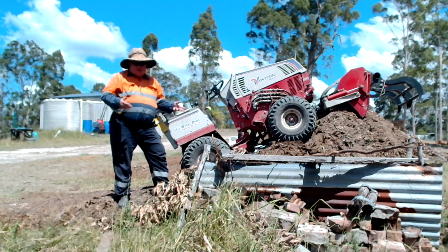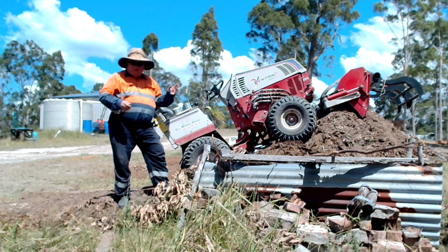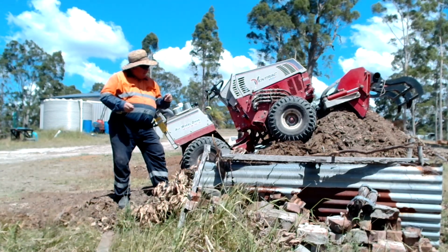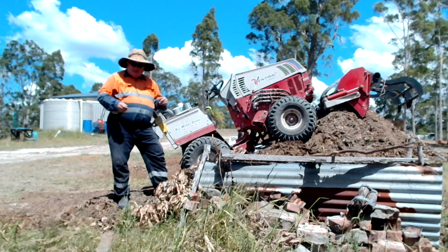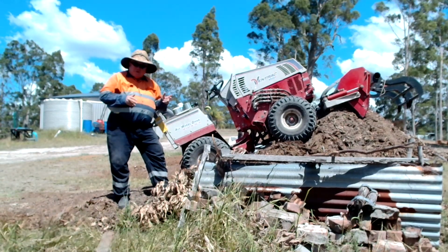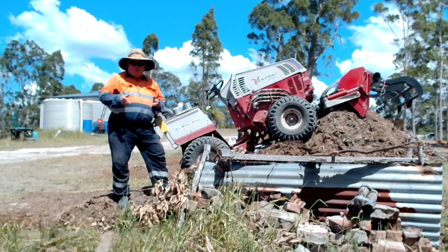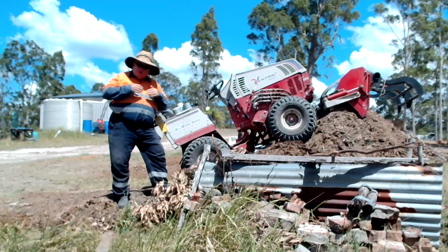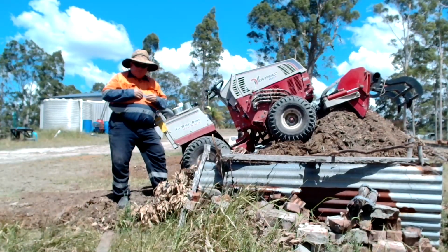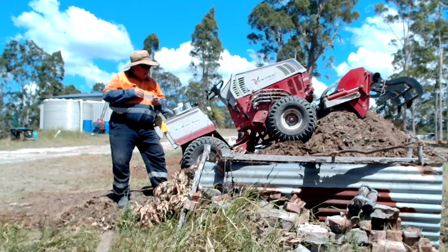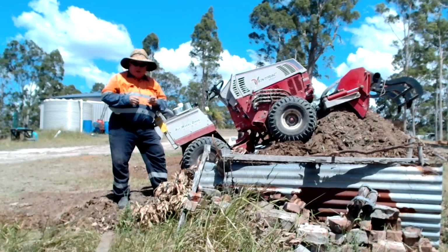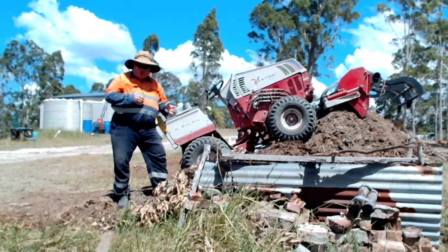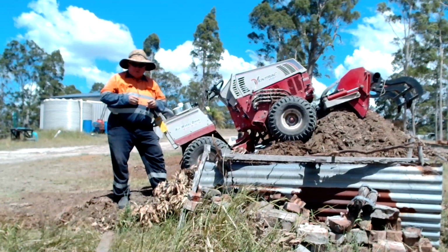So ultimately, I chickened out. This is only 25 degrees. Took a little bit of work. Had to put the bucket in harder to get it to stay there. But 25 degrees is about 1 in 2.1. So that's effectively, for every 2 steps forward, you go up 1. It's quite a steep grade, and definitely not one you would want to operate on for any long period. You definitely don't want to walk on it, again, particularly on loose material.